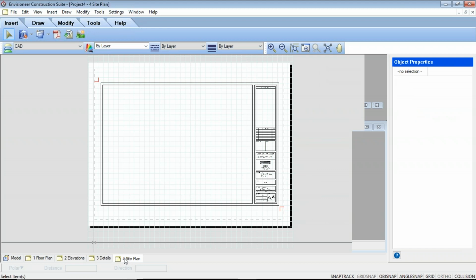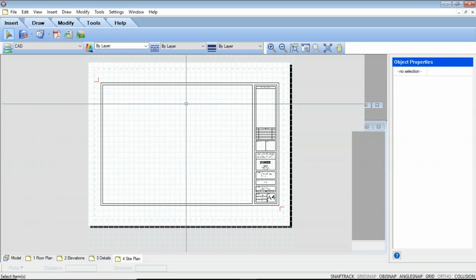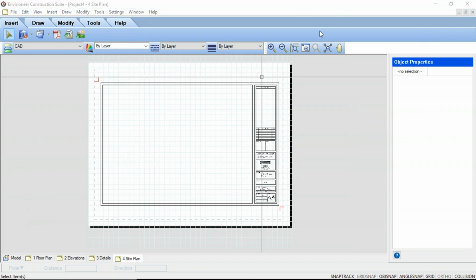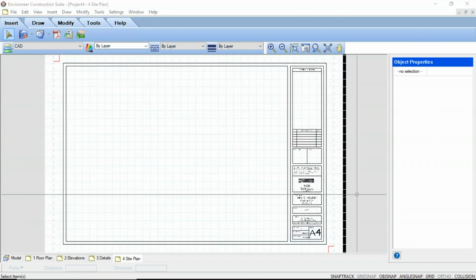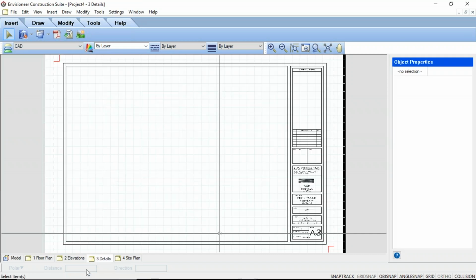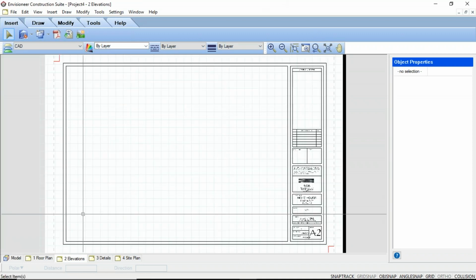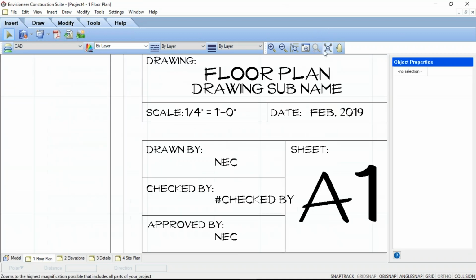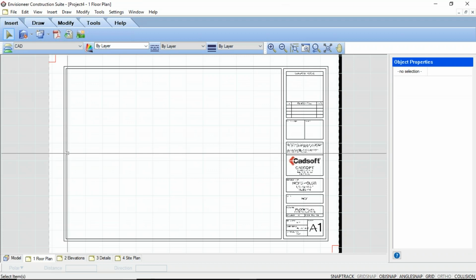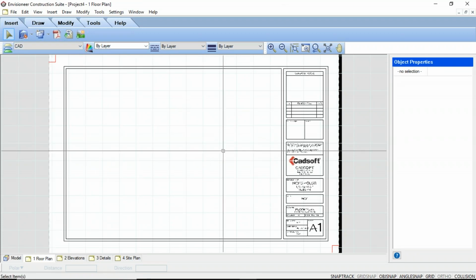Just one other quick note too when you're working with these is I always try to make sure that once I've made an adjustment on a worksheet like this, I use the zoom tool just to zoom it back to full. And I do that all the way through. It's just a cleaner way of going about it. So that way, when you go to insert your actual floor plan onto that sheet, it's just a matter of inserting it. You're not having to worry about zooming in or out.